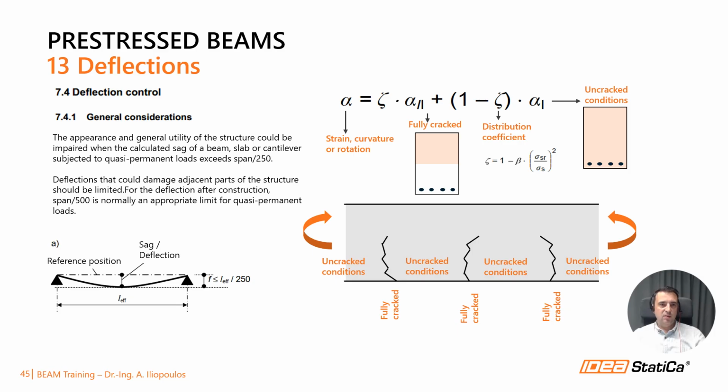The beam can also calculate the deflections taking into account the concrete cracking. It is a well-known fact that the maximum deflection must be below a certain limit in order not to affect the appearance or the serviceability. So when subjected to bending stress, cracks appear in the concrete, causing the concrete to go into the cracked state where the stiffness is minimal.